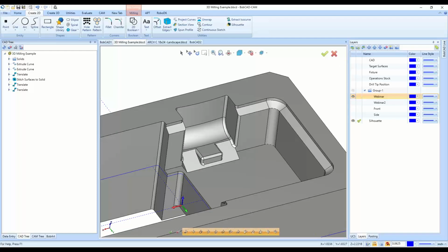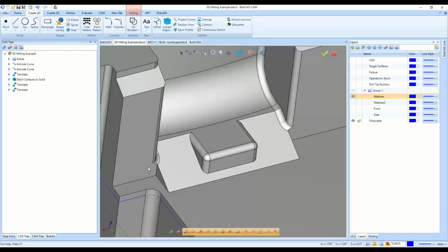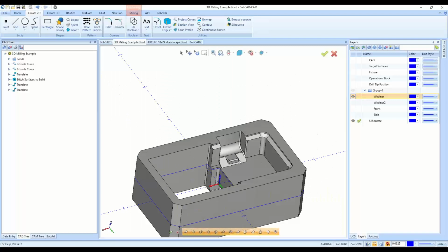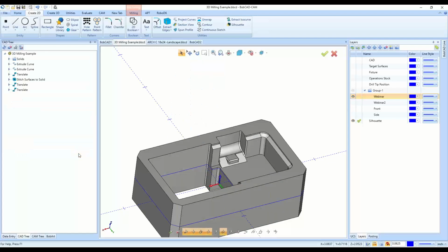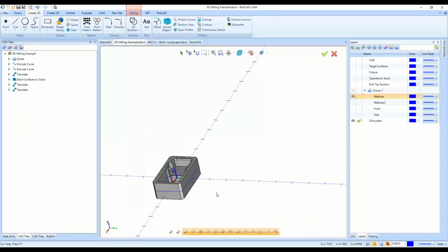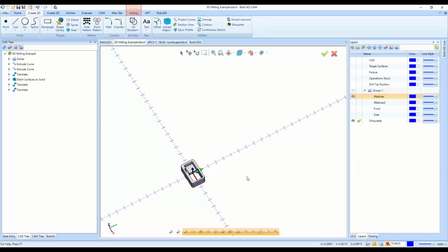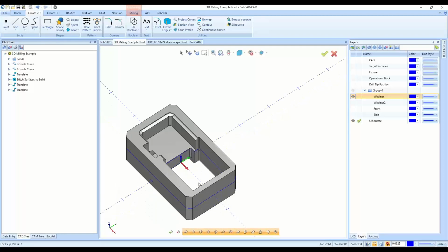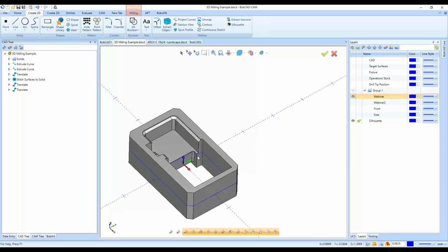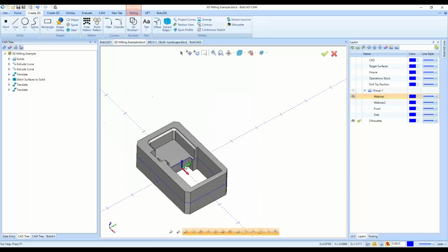If I go here to the top right, in between all of this geometry here, the silhouette will be able to pick this up, versus the section view, which is more of just getting a section view from the 3D model for dimensioning. That was mainly what it was for, but I kind of got away with using section view for everything. The silhouette is much more helpful for creating boundaries on the inside of parts and those types of extract edges options there, basically.